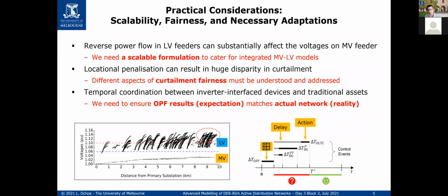Okay, Nando, but let's suppose that we can actually control them. Fine, you can control them, but there are delays as well. So an on-load changer literally has a physical element that changes the tap from one position to another. That takes 60 seconds, all right? Because it's not just about the data arriving, it's because it's a mechanical thing to do. It takes 60 seconds. It's not a beautiful power electronic thing, all right? So you need to consider those 60 seconds to avoid other things as well.